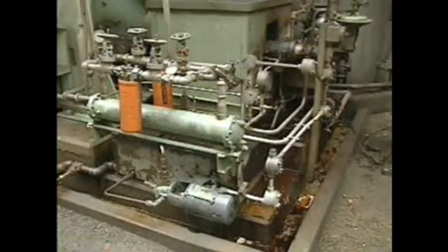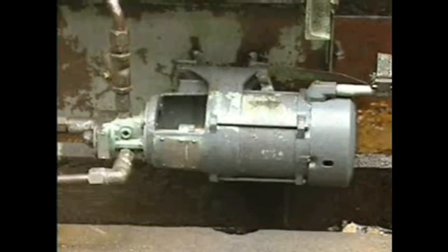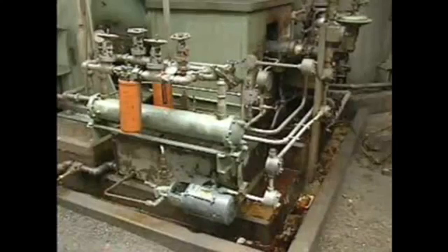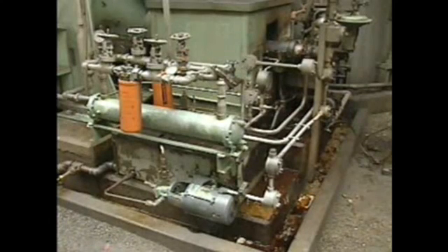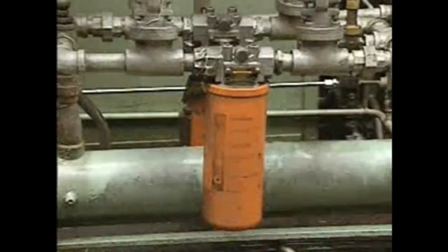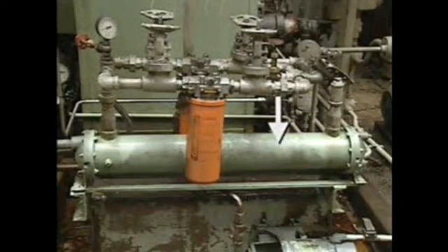A forced circulation system is a common method for lubricating rolling contact bearings with oil. In this system, a pump supplies a steady supply of oil to the bearing. The pump sits on top of a rectangular reservoir called a sump. After leaving the bearing, the oil collects in a reservoir so that it can be pumped again. Oil filters in the system remove dirt and contaminants from the circulating oil. Coolers are also used to remove heat that the oil picks up from the bearing.